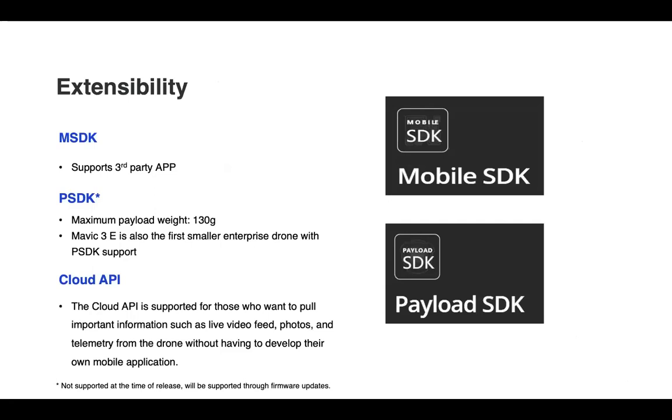Another great thing here with the Mavic 3 Enterprise series I know a lot of folks are excited about is MSDK support at launch. So it supports third-party apps running on the controller itself. So that is Android-based system, and that supports our Android v5 SDK. PSDK is not supported at the time of release, but we'll add that in future firmware updates. Maximum payload weight there is 130 grams.